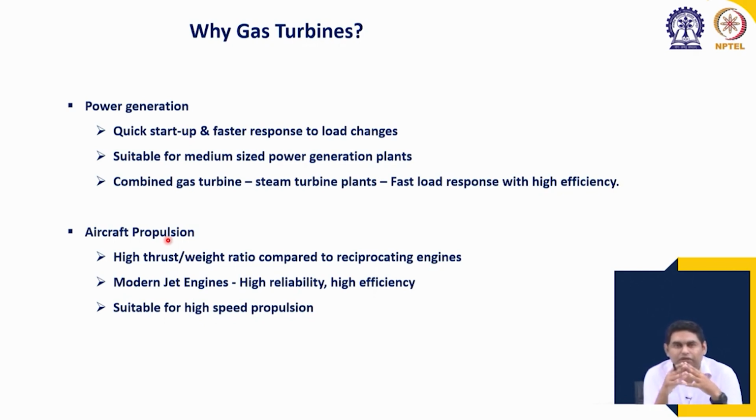If you see the World War I aircrafts or even World War II aircrafts, you will see famous examples of reciprocating engine based aircrafts. Very clever designs were made, and although these were fully capable of flying, there were many limitations. One was that the system was too bulky. You cannot use just one or two reciprocating engines, you need a very large number, 9 or 11 engines, arranged in a circular fashion, so as to make the power delivery as uniform as possible.